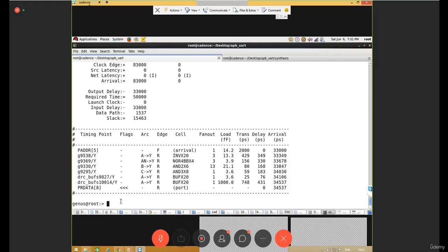How will you finalize the value? There will be a report in the form of CPF, where they will tell you that if the power is this much, you can take it forward, or else you have to optimize your circuit, do some RTL modifications or some SDC modifications from your side, so you can achieve the particular value they have given us.